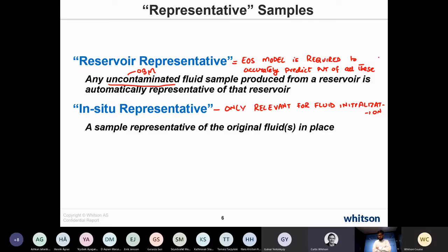But if you have these samples that are production samples that have no oil-based mud contamination, those are the ideal samples and PVT data to develop your equation of state model with. So that's the long answer to a very important question. But we just avoid using contaminated samples with PVT data unless we have to use them.